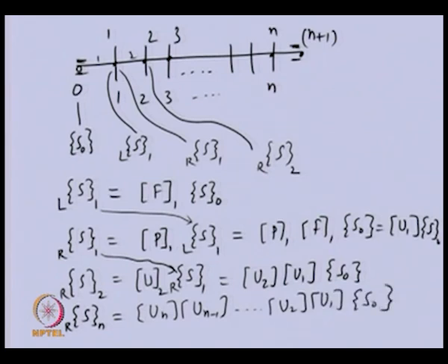So, that means right of disk n is this one, this is the state vector. This state vector we related with the state vector at the far end of the shaft using multiplication of these transfer matrices, and now another shaft segment is left out. So, we want the state vector, let us say, at n plus 1.